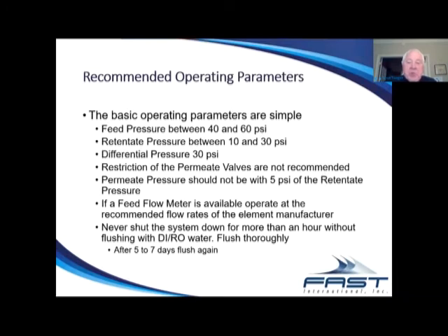Operating parameters are pretty simple. You want between 40 and 60 psi feed pressure, between 10 and 30 psi retentate pressure, for a differential pressure of 30 psi. We do not recommend the restriction of the permeate valves. Some people for a while thought that they would get longer life if they restricted the permeate valves, but we've also seen a lot of instances where your permeate pressure gets too high and you don't know it because you have no pressure gauges on it.